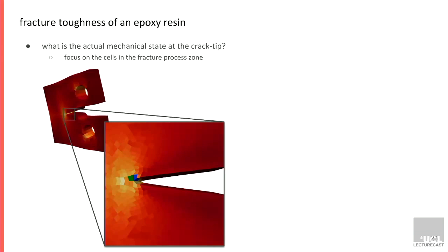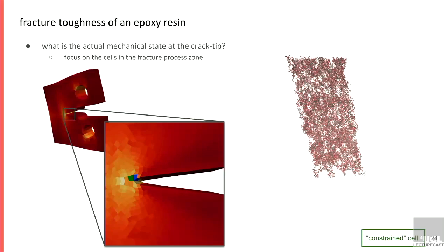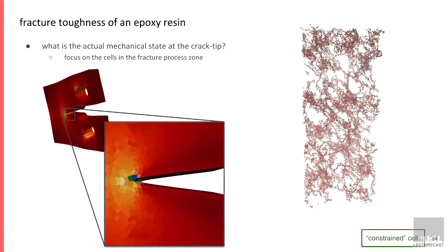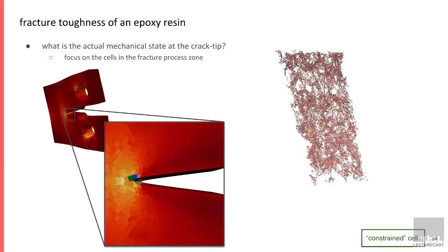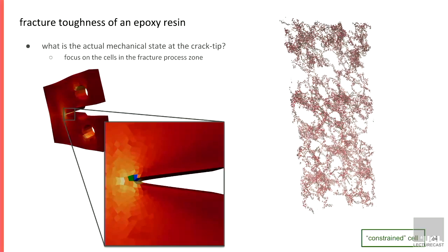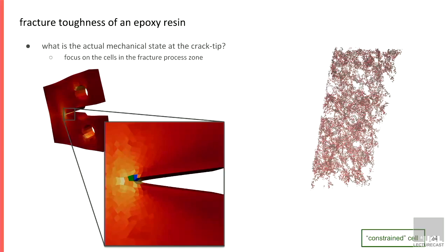What I want to show you is the comparison of what actually happens in those cells at the crack tip, what kind of mechanical state they face, compared to what is hypothesized in these single scale or hierarchical multiscale methods using pure tension. This is how the green cell is deformed when you pull it as part of a compact tension. It's no longer just a pure tension, it's actually a biaxial tension. You pull in two ways, and then you have shear on top of that.